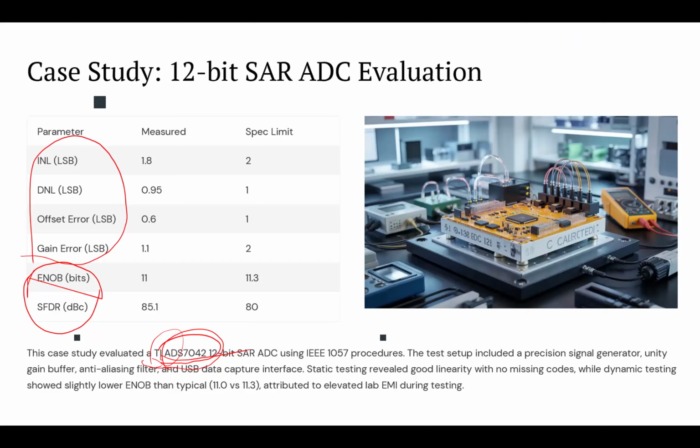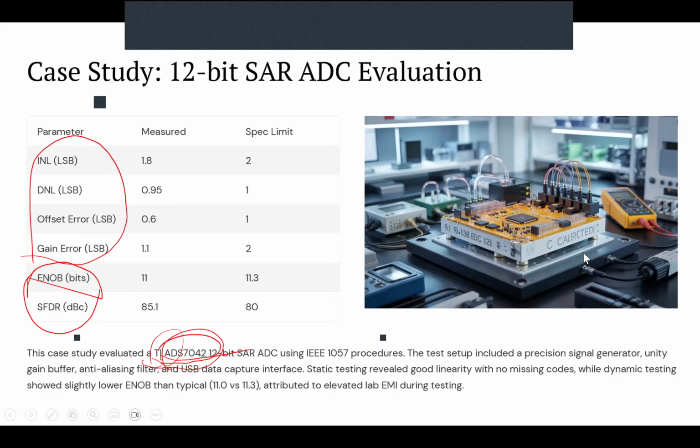Would it enhance it or not? Or we could have USB noise, switching power supply noise, or an unshielded laptop when we do the FFT analysis. So all these could be important. And after we address these issues, it could help us to improve the result.